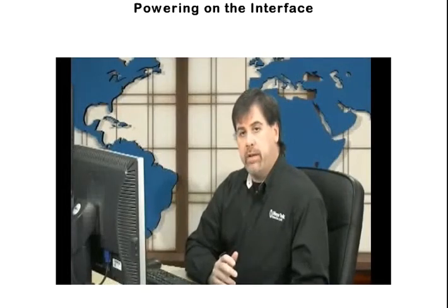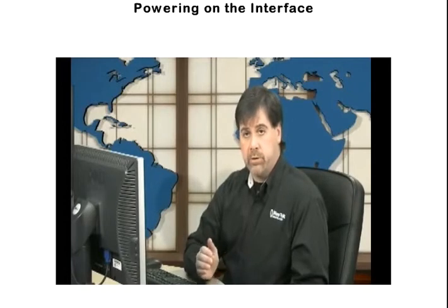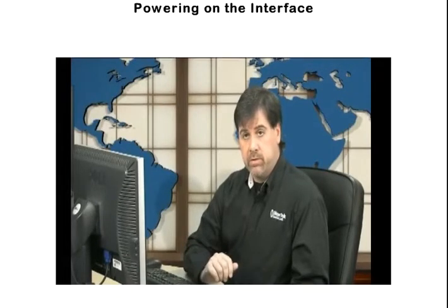Depending upon what sort of video input we're using, you'll have different controls available to you in the proc amp area. If we're using YC or composite, we can use brightness, contrast, hue, and saturation. If we're using a component signal, we can use the U and V offsets.